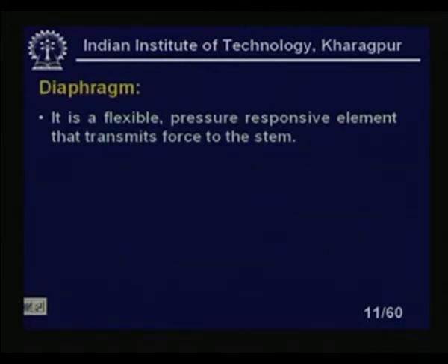Diaphragm. It is a flexible pressure responsive element that transmits force to the stem. It is at the top of the control valve. It is a steel diaphragm. We have already studied diaphragm, gauges, all these things. This is basically giving the force against the spring, which is already in existence, to the stem, so that the stem will move down as well as the plug will move down. It will go on and cover the seat of the control valve.